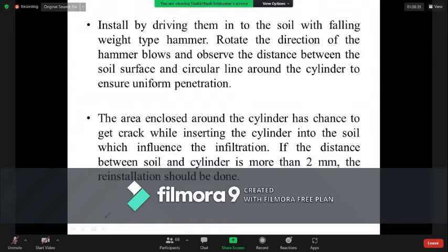So once you dig a hole in the surface soil horizon, you have to insert. So once you dig a hole more than 10 centimeter, think it's 15 centimeter depth you dig. But the height you need to insert is 10 centimeters.